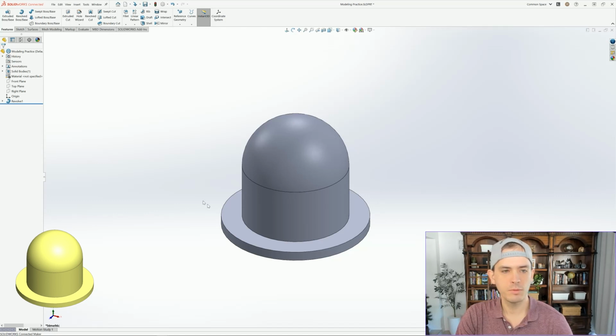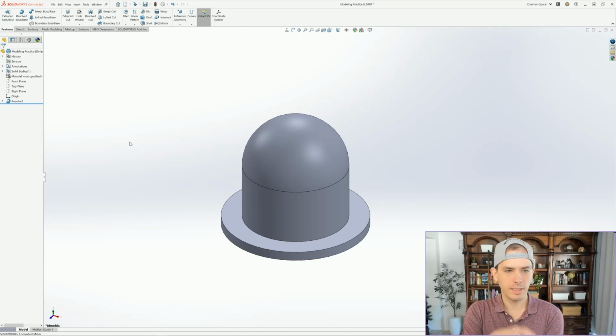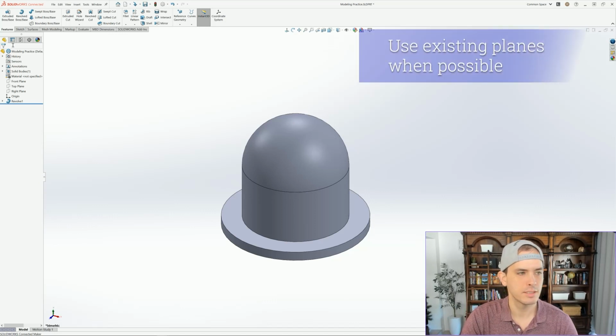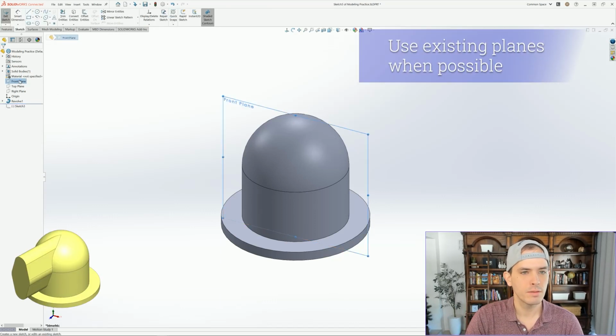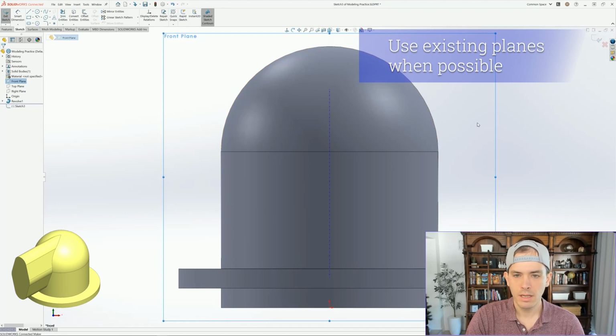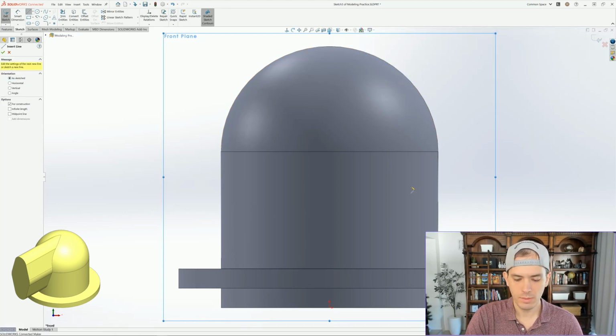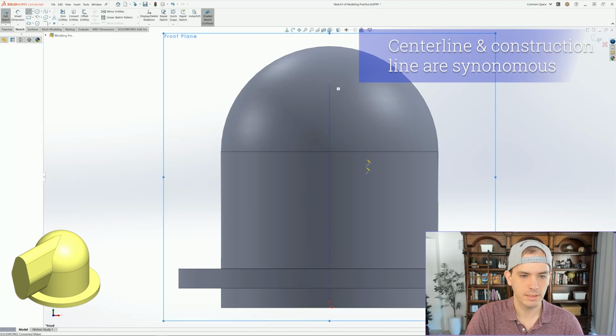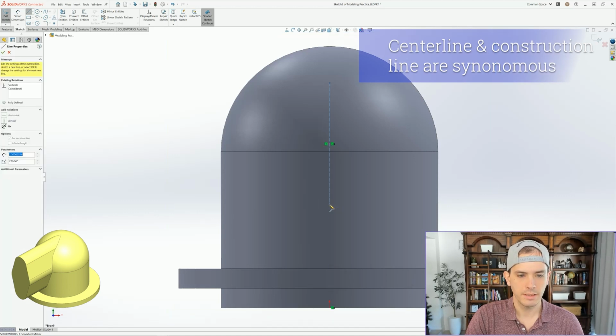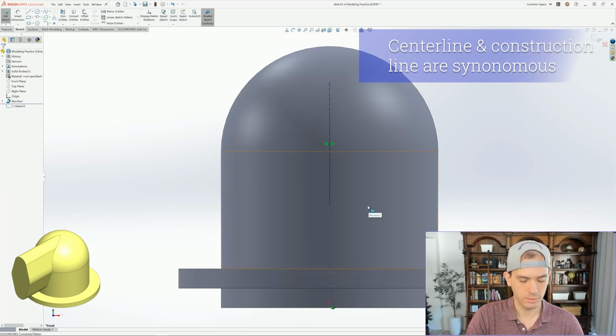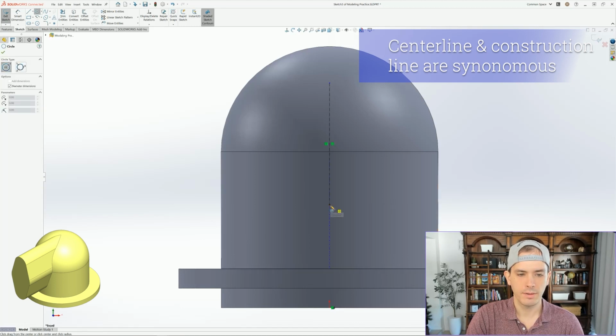So now let's move on to the next section, which I'm going to draw that extrusion that's in section CC here. All right. So front plane, again, another center line here this time. Always drawing these center lines. I'm just going to click it here to here. Remember, yellow indicates that those are going to be defined or added.